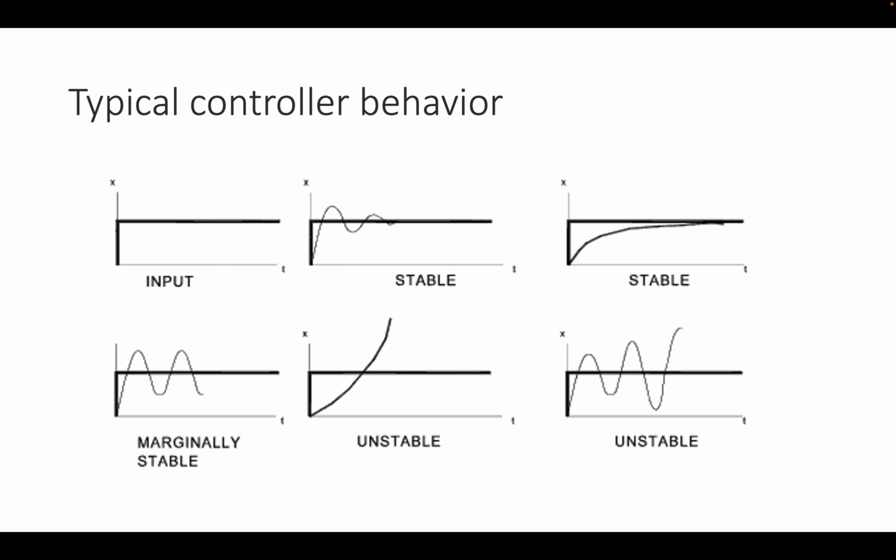If you would increase the sampling time of your controller, you would be able to see other behavior, including this one, because then the robot would have enough time to actually overshoot and then turn back. So I let you play with this a little more in Webots.